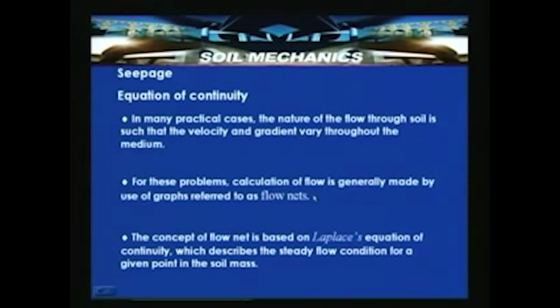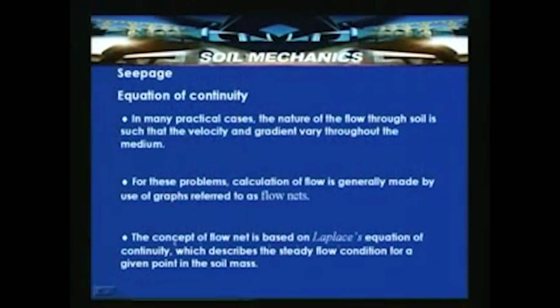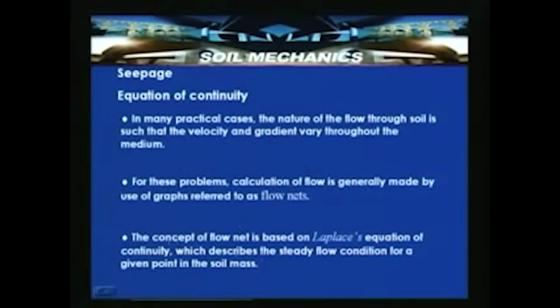This flow net method is nothing but the solution of the equation of continuity, which we are going to derive very shortly. The concept of flow net is based on the Laplace equation of continuity, which describes the steady flow condition for a given point in a saturated soil mass.